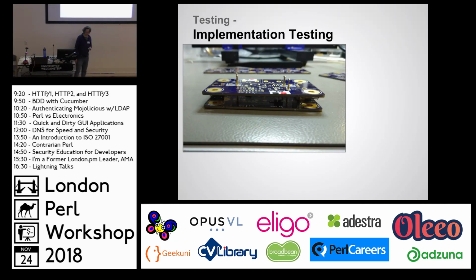Well, we build lots of test equipment, as I said. And so this was an exciting idea I had. I had some boards where the silk screen printing, basically the little white text on the top, the fabrication company had just happened to mess up the silk screening. And so I had these spare boards left over. So I ended up building these into this little, it's called a bed of nails, where you have all of these little spiky pins that stick up that make connections onto another board.